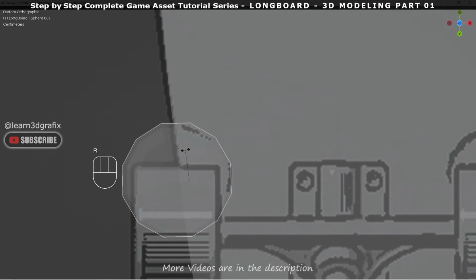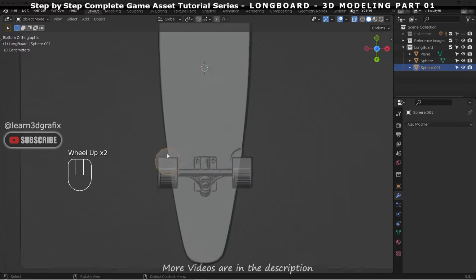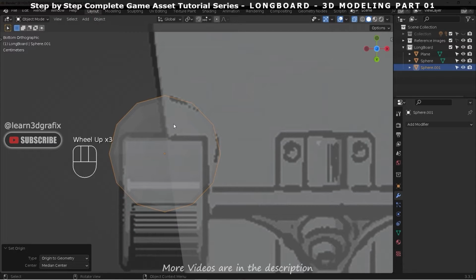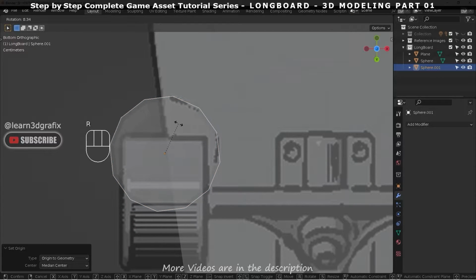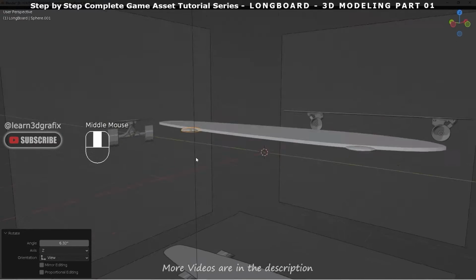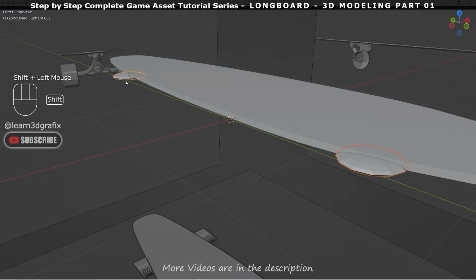The origin is not in the middle of the sphere. That's why it is not rotating from the middle of the sphere. Go to Object, Set Origin and Origin to Geometry. Now we can rotate the sphere from its center. Press Shift and select these two spheres. Press Ctrl J to join them.